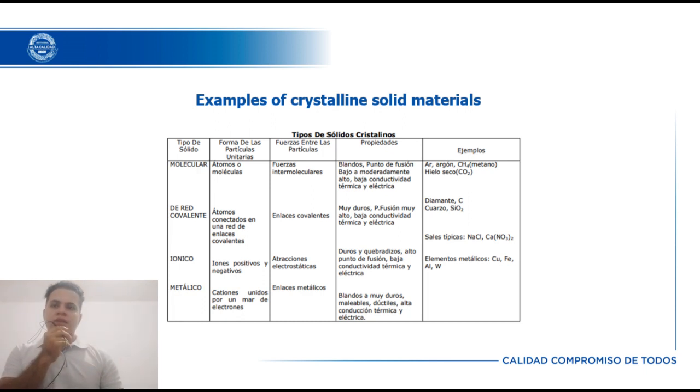Third, diffraction. Scattered X-rays are reflected by atoms in the sample in specific patterns, depending on the crystalline structure of the materials in the sample. This phenomenon is called X-ray diffraction. Fourth, detector. An X-ray detector records the scattered rays and the intensity of diffraction at different angles. Fifth, data analysis. The collected data is analyzed to determine the angles and the intensity of diffraction. This data is then compared to a database of known diffraction patterns to identify the materials present in the sample and their crystal structure. What are the applications of XRD?